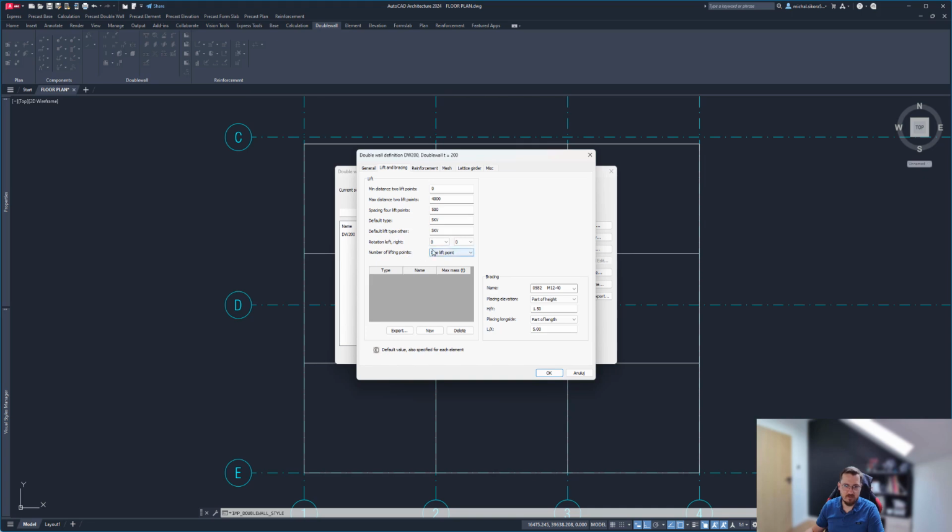So for example, we don't have anything defined for one lift. I think it would be not practical in terms of walls. 2 lift points, more stability to that, and we have 2 definitions for max weight of the element. So elements up to 2.5 tons, that's lift number 143, up to 4.5 tons, and that's lift 145. And 4 lifts, that's the second lift type, so 145, but we have 4 lifts for elements over 4.5 ton and less than 8 tons.